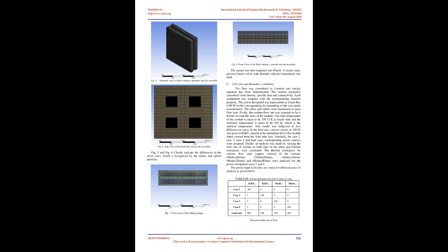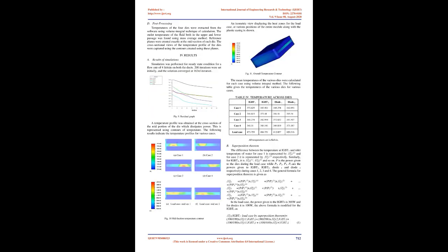Temperatures of the 4 dies were extracted from the software using the volume integral technique of calculation. The outlet temperature of the fluid in both the upper and lower passage was found using the mass average method. Reference planes were created exactly at the midsection of each die. The cross-sectional views of the temperature profile of the dies were captured using the contours created using these planes.